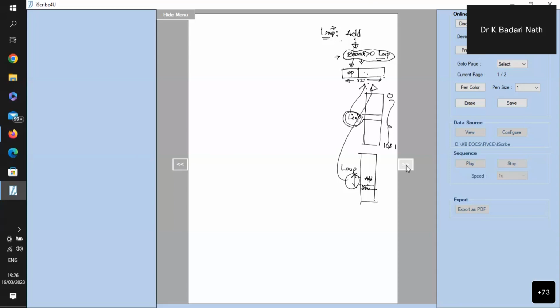So that is why almost all processors provide a facility of indicating the offset from the reference where you are executing. From that place, how far is your label? Then the number of bits required to encode that offset will be very small, instead of absolutely specifying the actual address from 0 to 1 GB. So this concept is used. Now, what is the requirement here? I should know where the reference is, that is, from which point I have to compute my offset.